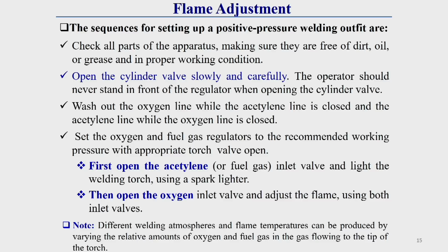Then generally open the cylinder valve slowly and carefully. We should keep this in mind. When we go for opening the cylinder valve, at that time the operator should never stand in front of the regulator. The operator should stand beside the regulator. What happens when opening the cylinder valve?